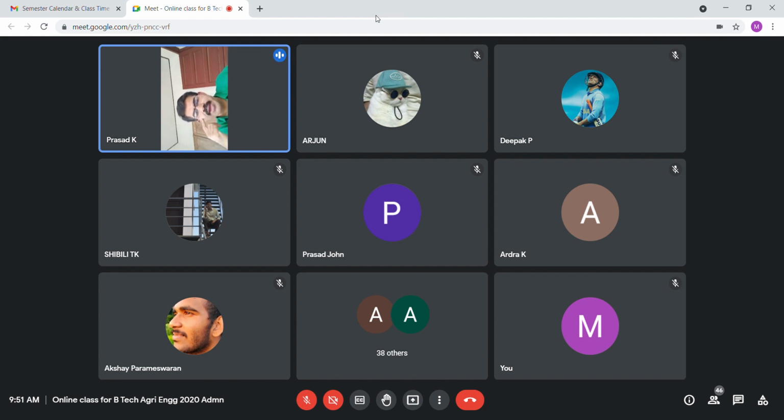Backlash. It is the difference between the tooth space and the tooth thickness. Next, what is meant by face of tooth? How can we call it a face of tooth? It is the surface of the gear tooth above the pitch surface.